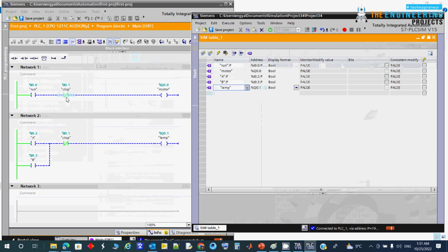Well done. Yes, because it is normally closed, so it is the reverse of the logic itself. So if it is true, then not true equals false. So that's why when it is false, not false equals true, meaning it is green. Okay, so now let's make this run to be on. So I just make this one true, as you can see.